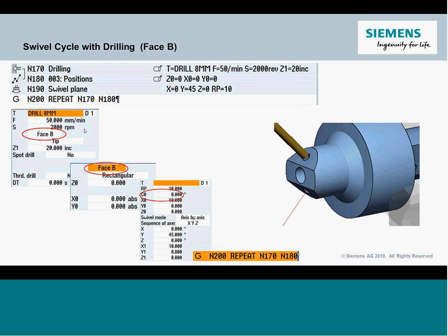Careful, if I'm driving a tool change, the plane may or may not have been maintained. It's really up to the OEM, when they go through their tool change macro, whether they want to cancel the plane or keep it active. So I would defer to the alternate: I'd rather be redundant with my planes from a safety perspective, because I know I just sent it through a tool change. So I'll actually add a plane in ours.